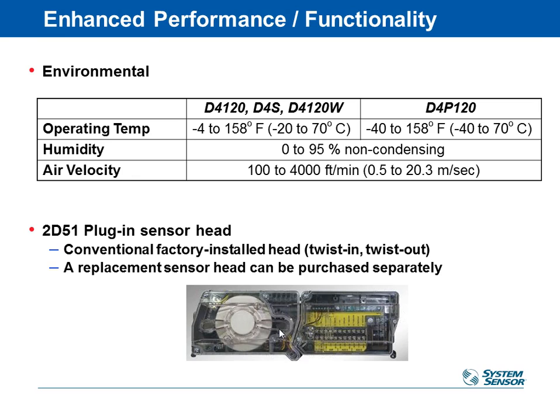As you can see on the screen there, it goes from 100 to 4,000 feet per minute. 100 feet per minute is obviously a very low velocity. So these guys, the exact same detector can be used in a standard system or in a low velocity system. Other manufacturers' products over the years would require you to stock and or buy 2 different SKUs for those applications. This guy can do both. So he can go all the way down to 100 feet per minute velocity on low flow systems if you have that kind of system installed.